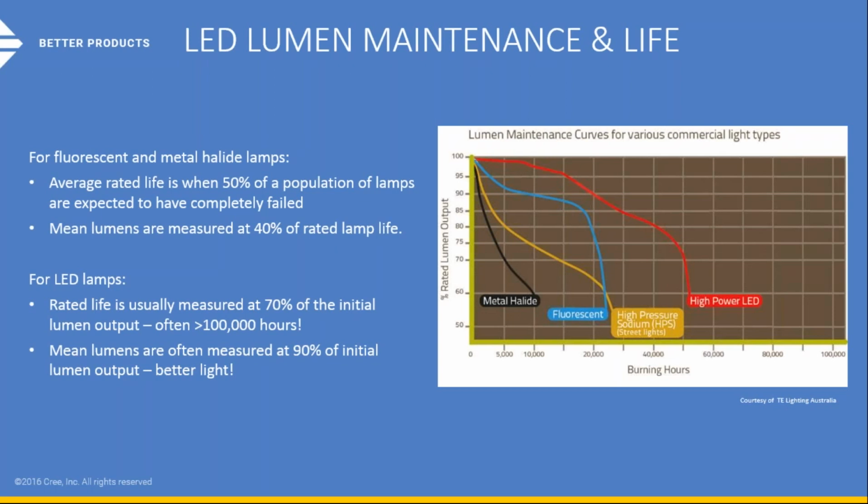Also, if you look at the number of lumens being produced at a given time, lumen output is fairly high for LED, even over a length of time, let's say over 50,000 hours. If you look at the 70% range, there is a number that the LED manufacturing world reviews. It's an L70 number, which tells us that is really the length of time that we envision the LED to be at optimal performance. Anything below that L70 number means it's potentially identifiable for an upgrade or a replacement, but it's still considerably longer in hours, anywhere up to maybe 20,000 hours longer than a standard incumbent technology product.